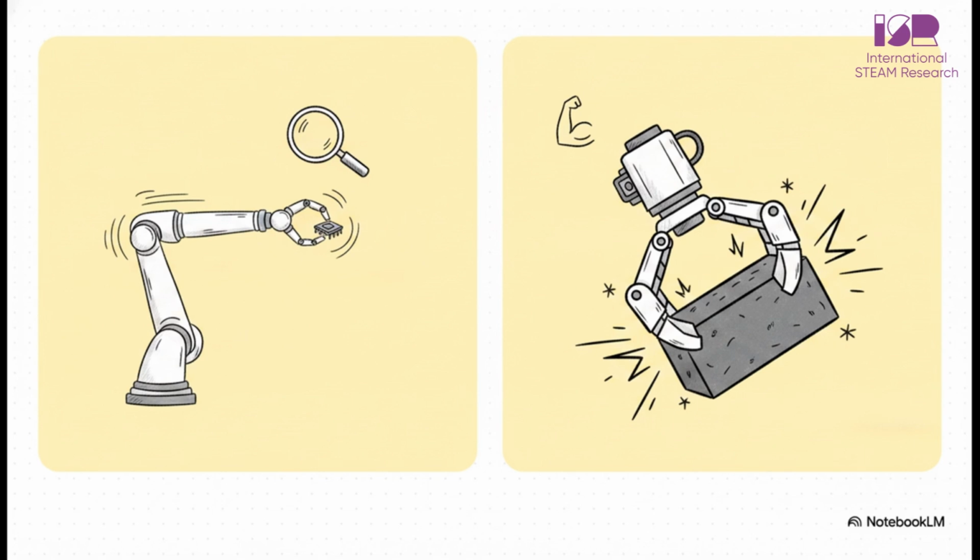But right next to it is the helical gear. Notice how the teeth are winding? They're used for parallel shafts just like spur gears, but that twisted shape actually allows them to transmit heavier weights at higher speeds, and they are way quieter. The catch, though? That twist generates a sideways thrust force, so they require special bearings just to stay in place.